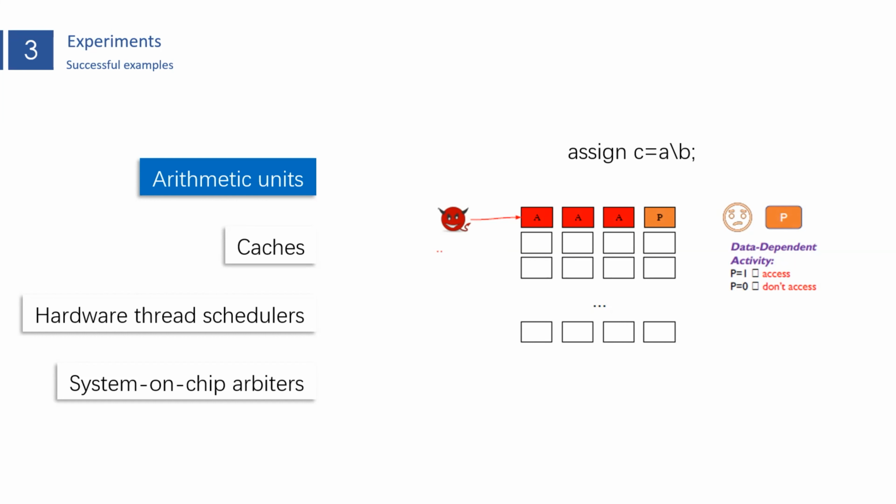That way, if I'm the attacker and we're sharing the same cache, I can easily perform a digital side channel attack on the information about A and B that I want to know, because different computation times are a large information leak. So what we can do is make the multiplier time constant, so that whatever value we pass in, it always takes the same amount of time to calculate.